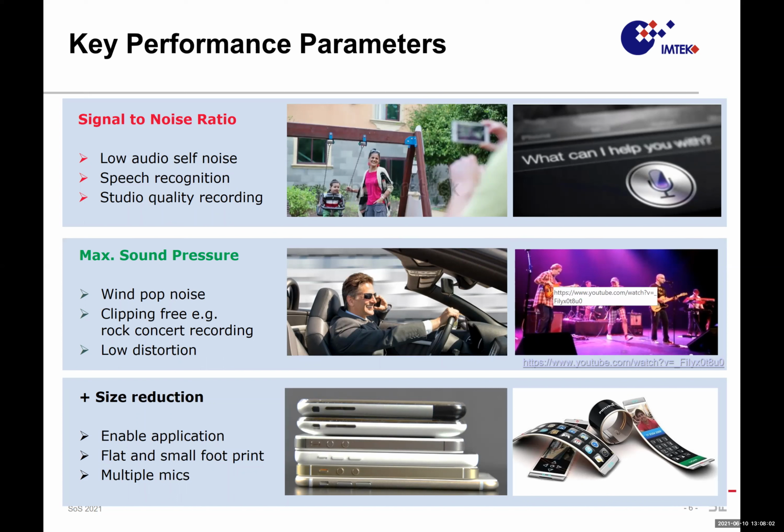And the lower this limit is, of course, the further or the more remote you can take recordings. Or in the case of speech recognition, understanding depends also on the noise level. The lower the noise level is, the better the microphone can take tiny signals or specific items in speech. And on the other hand, it is of course the maximum signal that you can transfer. So this gives the signal to noise ratio. It is quite an important parameter.